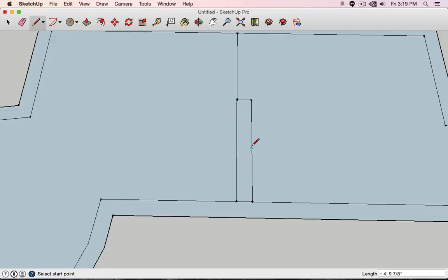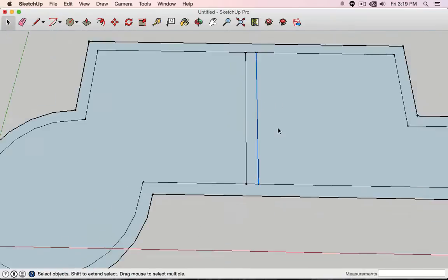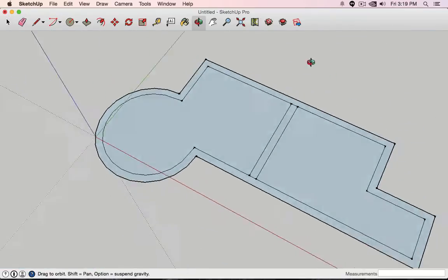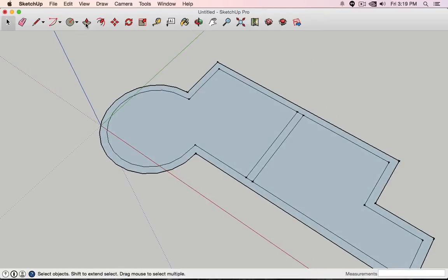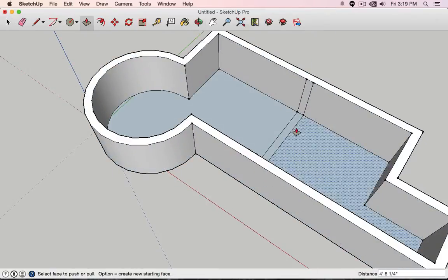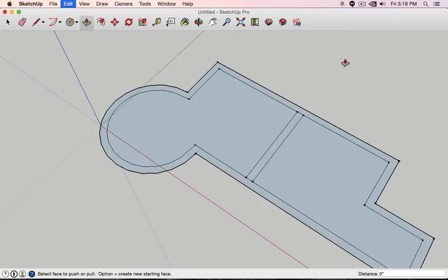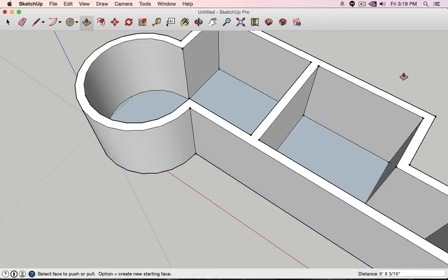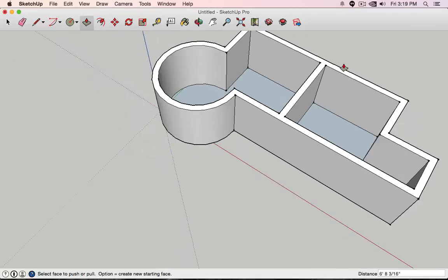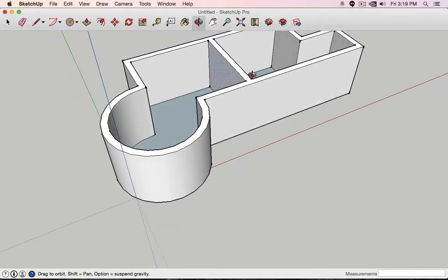And then click and click. See there, I drew 2 lines. Delete this line. Now this is 1 line. And if we extrude this, you see you have outside and inside walls, and that's not what I want. So I will go and remove those parts there. And then I can extrude everything at once together. Pretty awesome.